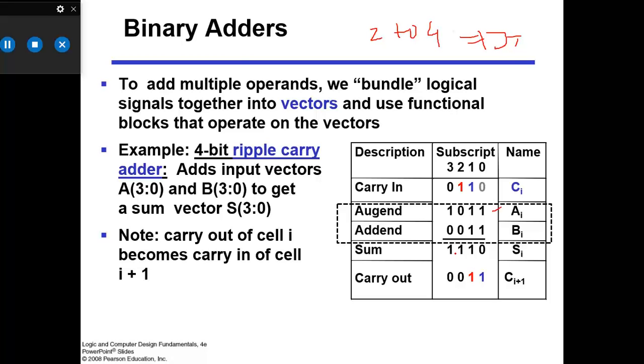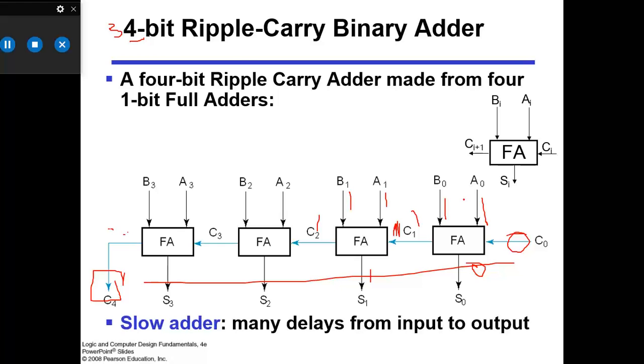So this is basically your answer. For the sum, you can say 1, 2, 4, 8: 2 plus 4 is 6, and 6 plus 8 is 14. So you can verify your answer by converting the binary into the equivalent decimal number, just to verify. So this is a solved example for a 4-bit ripple adder.